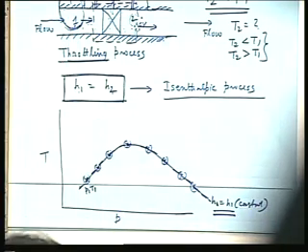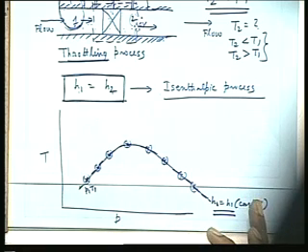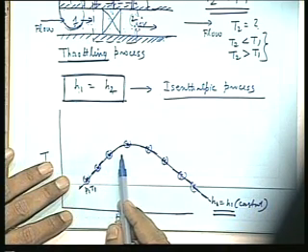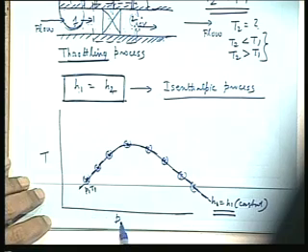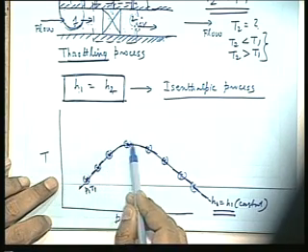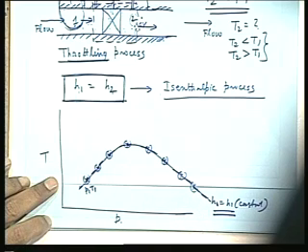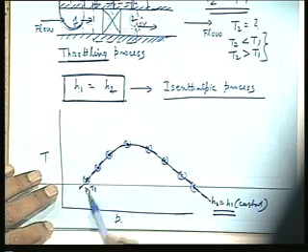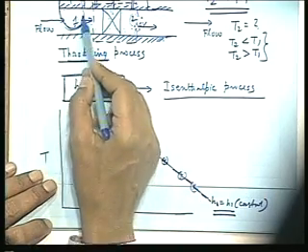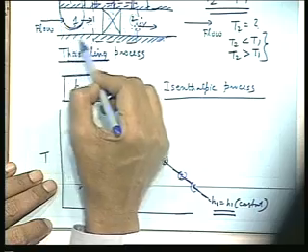This is clear. And if we generate this way a number of pairs of points with P and T having the same enthalpy, we can draw the locus of a constant enthalpy in the TP plane, and this will look like that. That means this will first increase, have a maximum, and then decrease. Clear? So this way we can generate a family of such curves if we now change this initial condition P1 and T1.